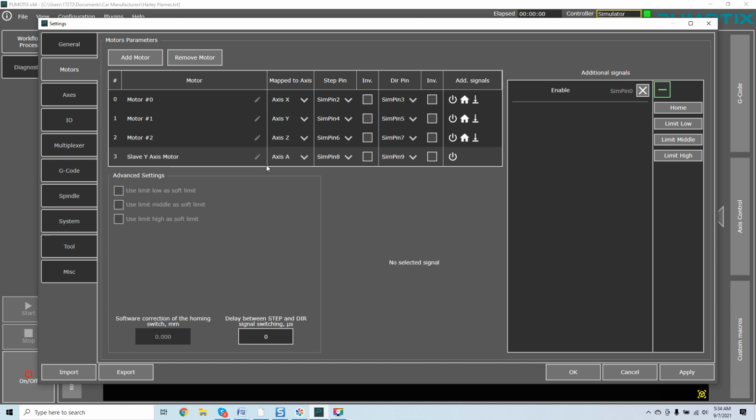In this particular instance, if you were dealing with a G540, it would be mapped, once again, to the additional axis. And with the G540, you would not use the A axis. I left this here on purpose. What you would do is map this to the Y. Now, what's going to allocate this to the A axis on the drive is how you allocate the step pin